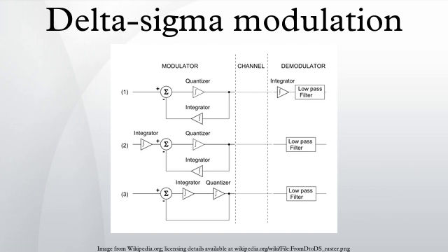The effect is that, for this example, the undelayed impulses will occur at clock points 0, 2.5, 5, 7.5, 10, etc., and the clocked impulses will occur at 0, 3, 5, 8, 10, etc. The maximum error that can occur due to clocking is marginally less than 1 count.